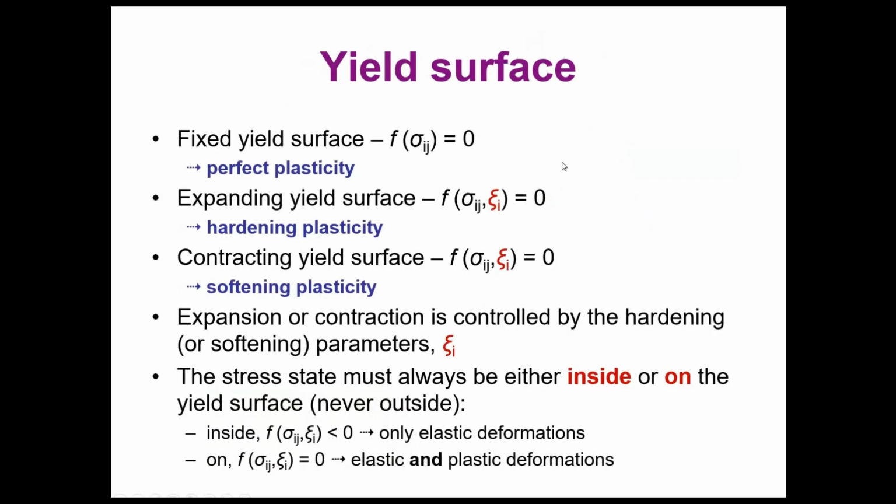If we recap a little bit about the concepts we have introduced, for example, the yield surface for a plastic theory is going to be a surface that is in function only of the stress tensor and plotted in a 3-dimensional space of the principal stresses.